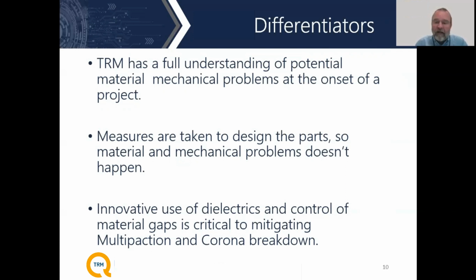For example, mechanically, it depends very much on where on the spacecraft it's located, as to how smooth a ride it's going to get going up at launch. Also, where it's going to be mounted on the spacecraft. Is it on a hot spot of the spacecraft? Is it on a cold spot? What sort of thermal environment is it going to see, and what sort of mechanical interface is it going to have with its next higher assembly?